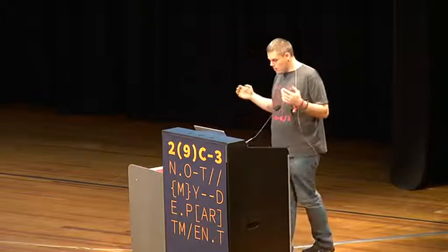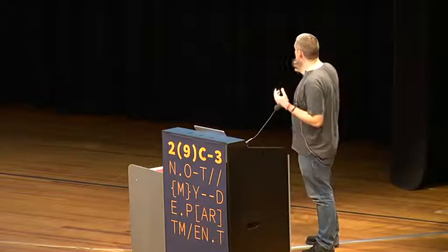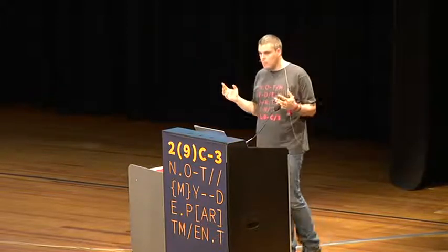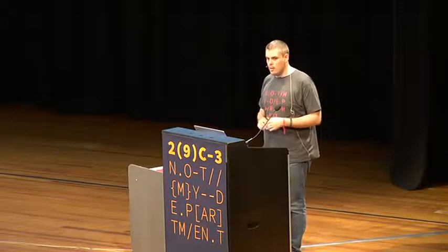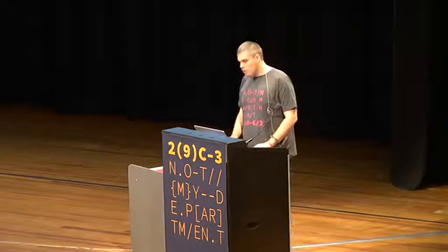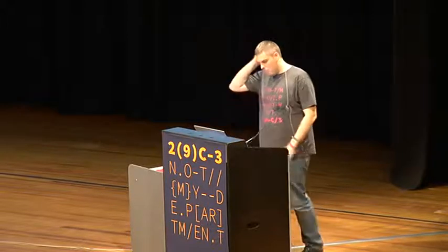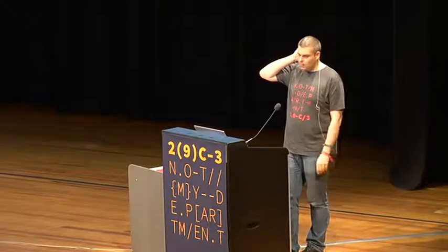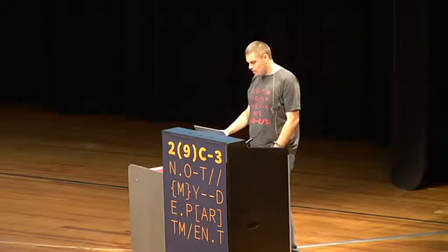Which means it's perfect for us because we can just take the main OpenBTS application, completely unmodified, and just replace the transceiver binary with our own that will, instead of using a USRP, use phones. Of course, it's easier said than done, because when you get to actually transmitting raw information on the air using the phone, things get interesting.